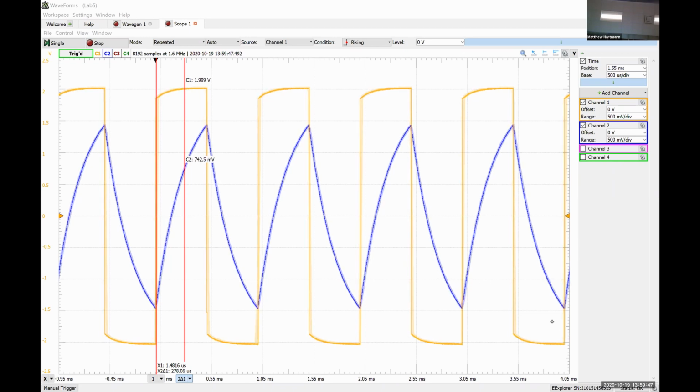We don't have any real reference point, right? Our capacitor voltage, we know how it's behaving at t equals 0 minus and t equals 0 plus, because it can't change abruptly. But if we were looking at, say, the capacitor current or something like that, even that measurement would be questionable because we don't have that fundamental relationship. And we definitely can't say that at t equals infinity, it has some value, because it's never settled. So this graph does not give us the required information to determine the total response of our capacitor voltage. And it's purely because the frequency is too high.